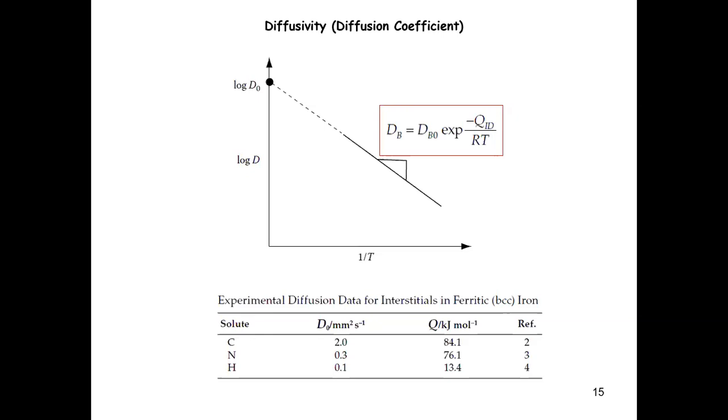So I have a question. D0 is higher for carbon, so does it mean it diffuses slower, or no? Look at the unit and consider the equation that gives you diffusivity or diffusion distance, if you have a distance x and time t. So a larger D0 typically means that, at least on this linear scale, carbon apparently has a larger diffusivity, right?